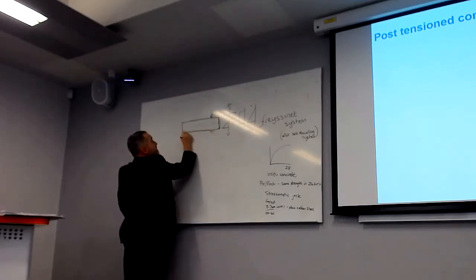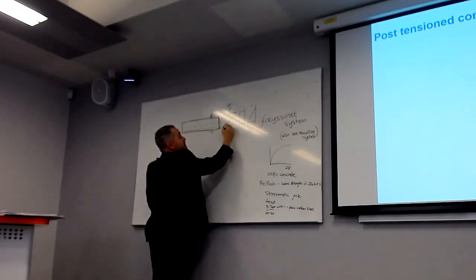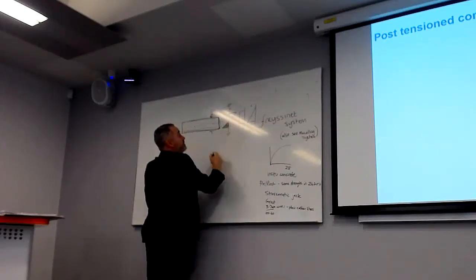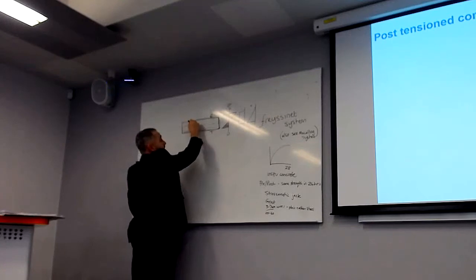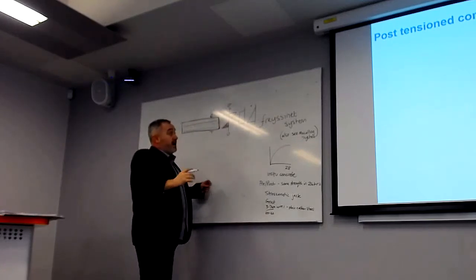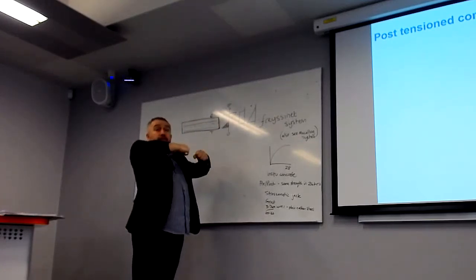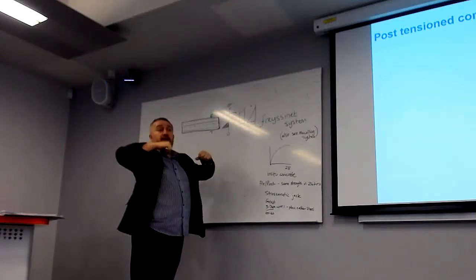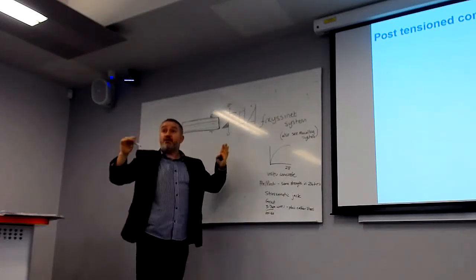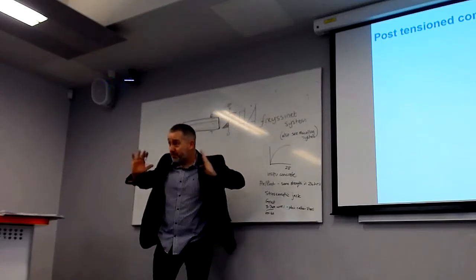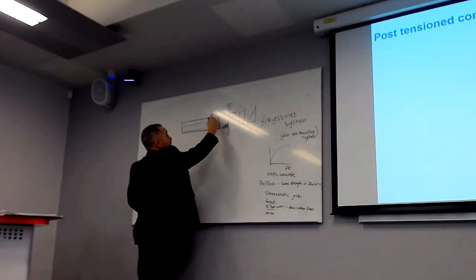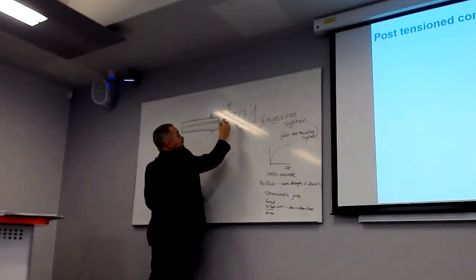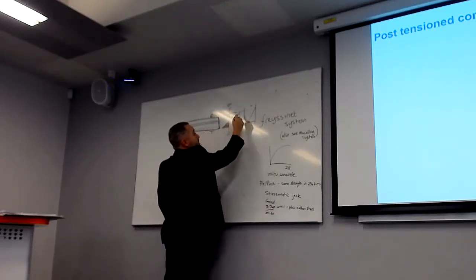So this is why we put our steel within there. So this is our tension. Now, if you put some additional steel in there, and you put it under tension, so that when you let go, you know, like when you pick up a load of books and you push it together and lift it up. So you put the whole concrete in, so you get some steel, put that into tension.